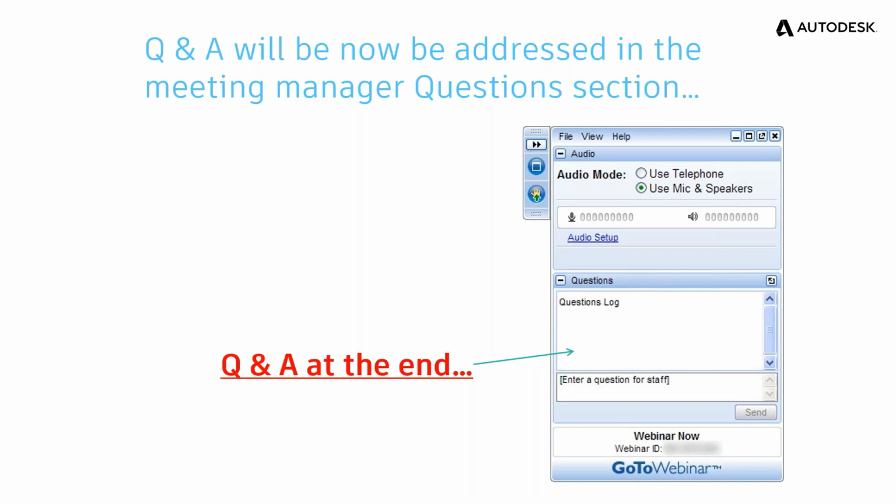How do dynamic blocks affect attributes? I think we need more information on that one. There's a couple of these we'll probably have to get back with you to answer because it's going to require some testing. They're going to affect attributes the same way as a normal block with attribute. You're going to have to use ATTSYNC to make it update if you've made a change to the block definition, and attributes could be shown in different visibility states. That's about it, though.